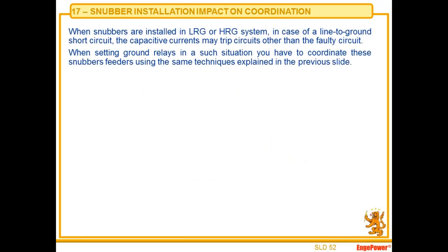The same thing happens in snubber installation. Nowadays, a lot of transformers are burning due to switching of vacuum breakers and small lengths of cable. So these overvoltages are burning transformers. And to solve the problem, people are performing snubber studies and snubber installation.